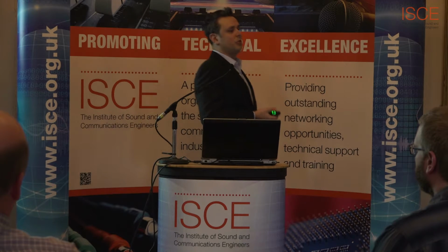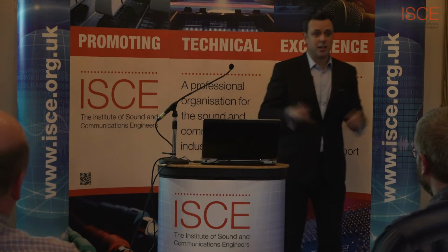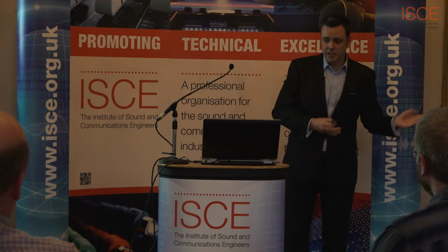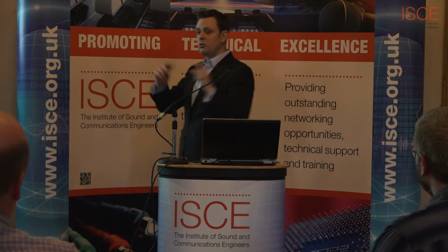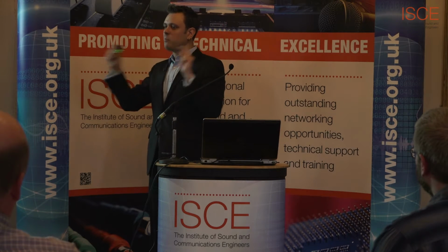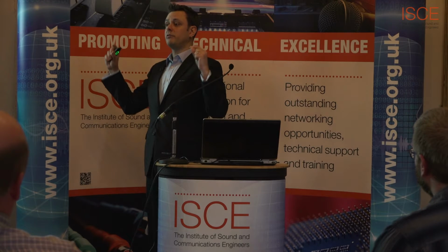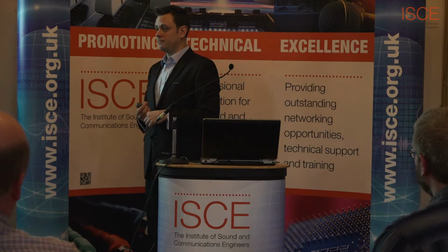Indeed, Cirrus Logic Peak Audio did provide a tool, now about 20 years out of date, called CobraCat, which allows you to work out how much bandwidth you're going to have from A to B and try to make sure. But by and large, you must certainly be protecting it with VLANs, i.e. trying to keep it away from other traffic, or you have to have a dedicated network and make sure that you're not going above what the network can cope with, especially on uplinks.